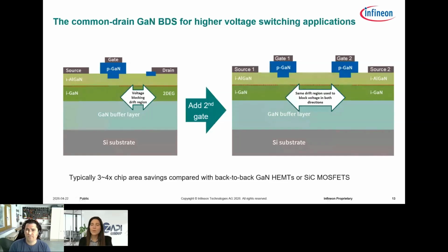Okay. And do you expect that the GaN BDS adoption to pick up sooner for onboard charging in electric vehicles, or do you think the motor drives might happen first? Well, it's really hard to say. I did mention that the Tesla Cybertruck already uses a matrix converter. So at least on the topology side, there's a head start for the onboard charger.